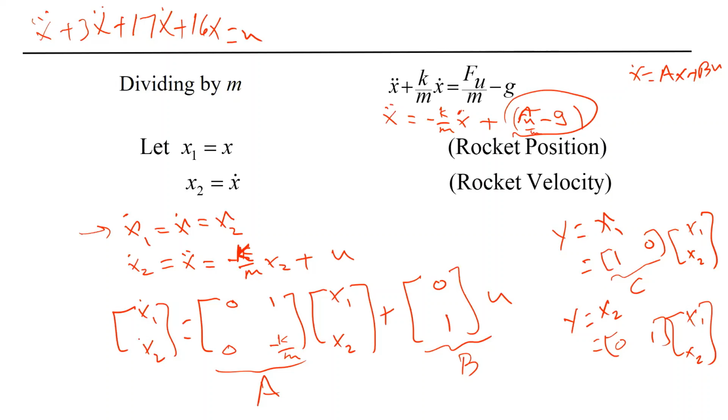What is the idea of finding y equal to Cx? Why do we need it? Because I want to put y in terms of the state variable. My system is A, B, C, D. I want to keep the states, the input and the output only. So I need to define my C matrix, and that will give me the relation. Maybe with examples it will be clearer.